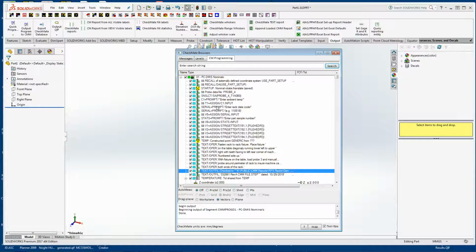In the PC-DMIS world, a number gets out of that input via this assignment mechanism. Assigned statements get translated into commented out DMIS assigned statements where the variable name equals assigned slash and whatever the expression was. The expression is not likely to be valid DMIS, so that's why they're commented out. I'll show how these can be handled editing the DMIS file. It's pretty hard for the loader to reverse engineer the intent that's going on.